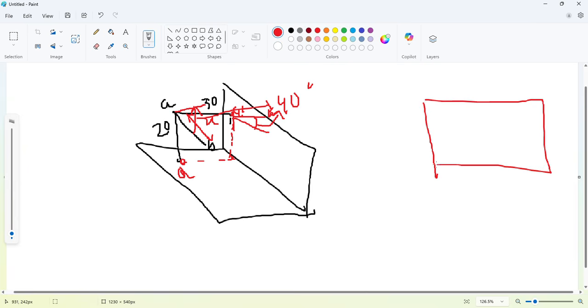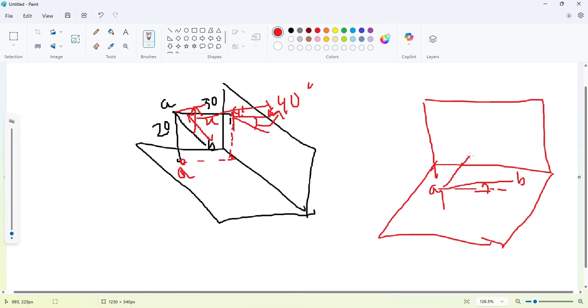So I can do one more thing here. Just this is the plane. Suppose this is a line here, which is at an angle of 40°. A, B, this length is X. So this is going to be A dash. This point is going to be A. Now, if this line AB is at 40° with HP, the front view is going to be like this. This is going to be B1 dash, and this angle is going to be 40°, which is visible in the VP.